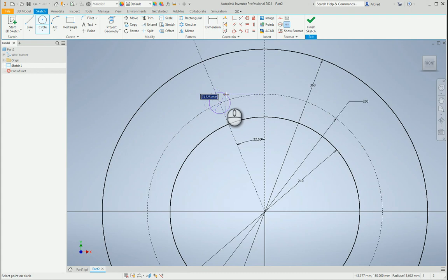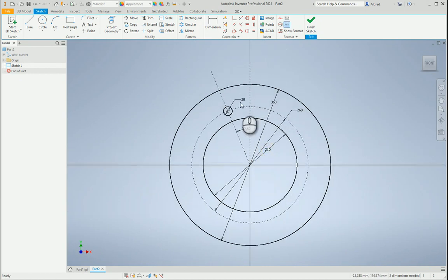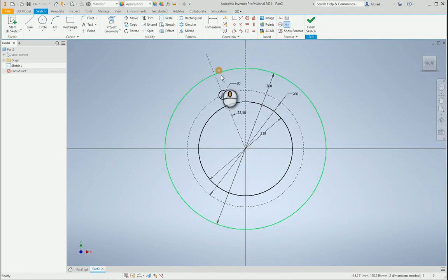So it's going to be sitting over there. The diameter of that, let's make it 16. Okay, 20. Okay, happy with that. So that 20 though, I just need to name it as well. Hole size equals 20, so that we can change it afterwards.